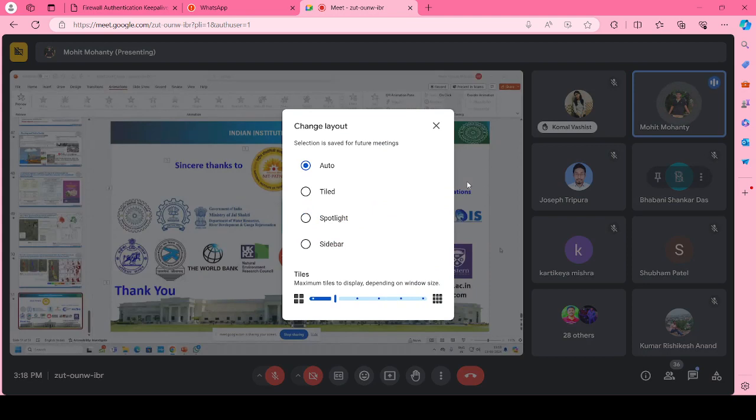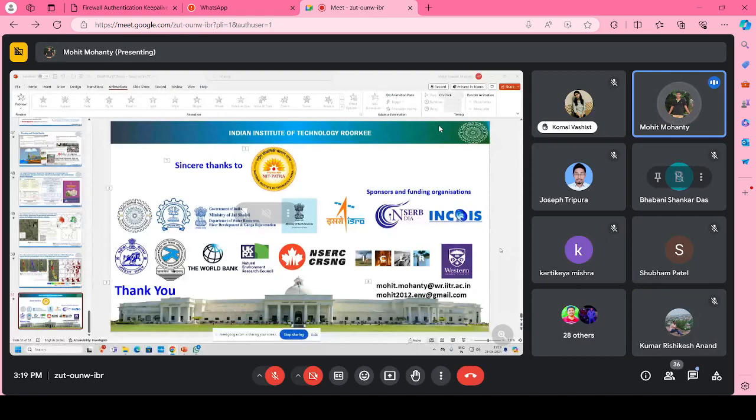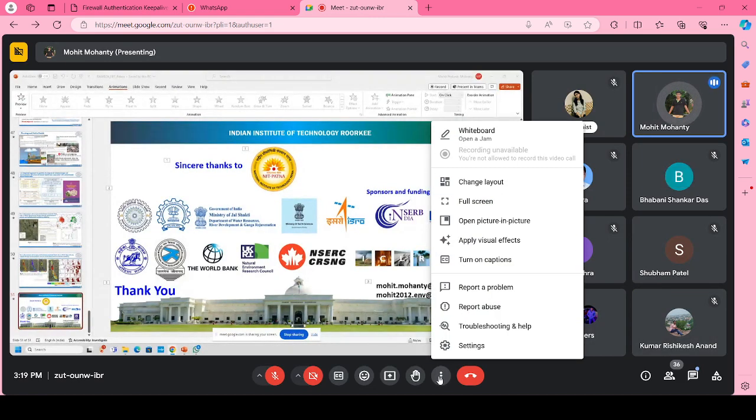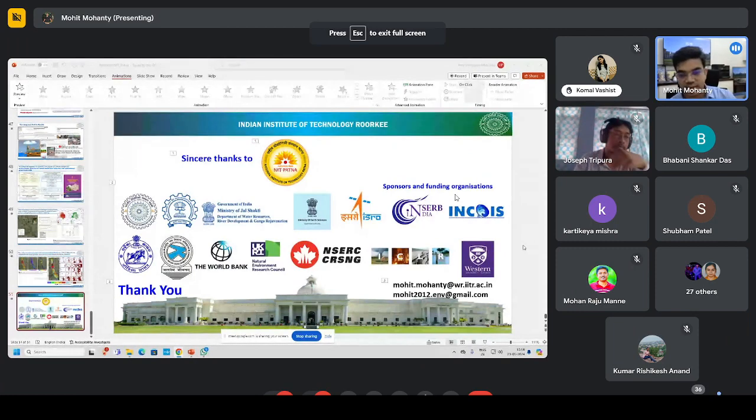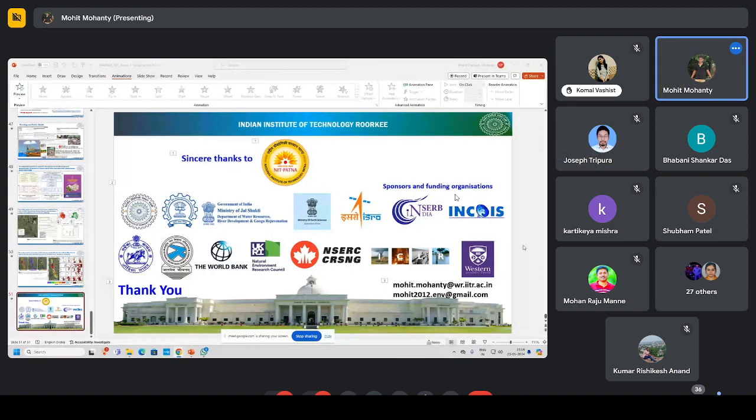But basically, for any flood model, the basic parameters are topographic data, rainfall data, streamflow data, and land use land cover, because you have to also take care of the Manning's roughness, and tide data if that locality is in a tidal catchment. These data are primary; they should be considered. Apart from that, if you want to use wind data or infiltration capacity, if it is available and within the range, and if they keep the model stable, then it's okay. Otherwise, I think we have to create some assumptions and go ahead.